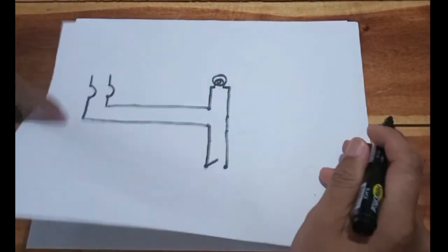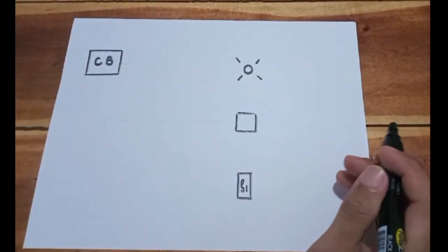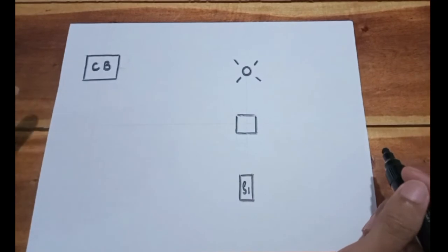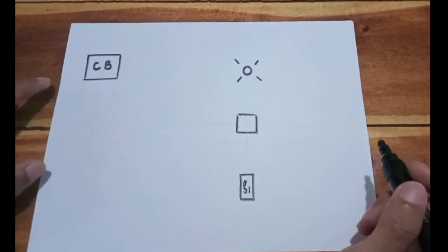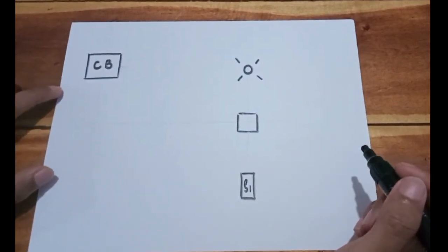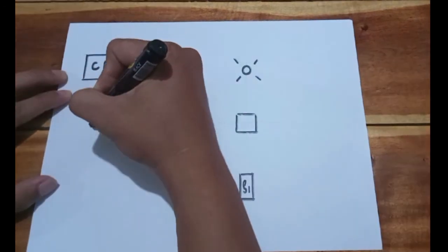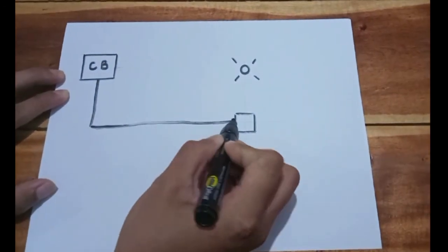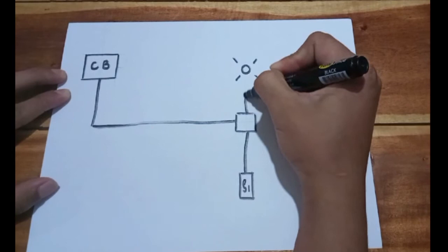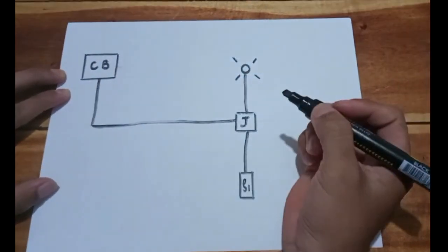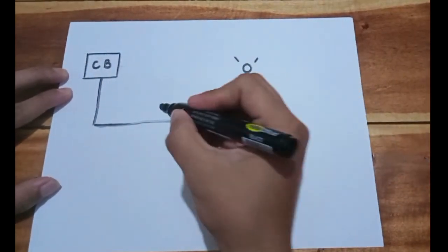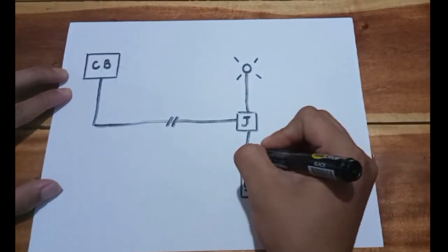In making a line diagram, we just put in the symbol again like the format of pictorial diagram, and then we just use one line in its connection: source to control, control to load, and load to source. We'll use a slash to denote the number of conductors in the line.